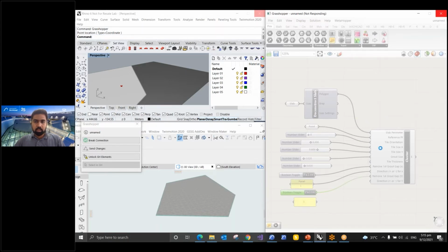But if you see here, I just have to create the extrusion here. And after creating the extrusion, I just need to pass it to the morph under the Design in Archicad category. So I just pass the extrusion inside the morph, which is the solid morph. And then once that is passed, we will get the morph created inside Archicad. We can change the layer, we can change the material of the morph using the morph settings component. Okay, let me just close this, it's taking a bit longer.